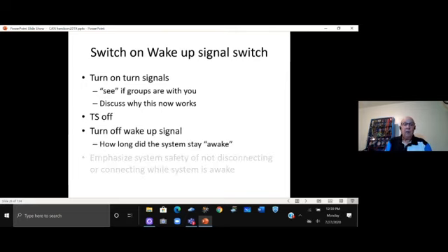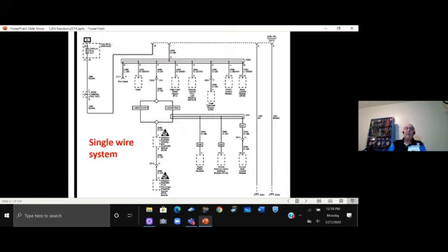Okay? And then when I go through this, rather than talking about it, I did it. I was live when we did it. Okay, let's zero in on a simple 1-wire low-speed system, and then we'll do a simple high-speed system. We start, and we have to recognize that there's battery in the DLC. So what pin is it? It's pin 16. If you have power in the DLC, you will also have ground in the DLC.